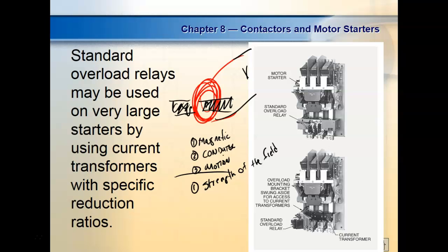So that means what's nice about a clamp-on ammeter is that we don't have to break the circuit. But normally they only work with what? AC. Yeah. So like I said, you can get them. We have a solid state device called a Hall effect sensor that can give you an analog output that represents a DC current. So some clamp-on ammeters will measure DC current if it's got that Hall effect in there, but they cost quite a bit more than just a standard clamp-on ammeter.